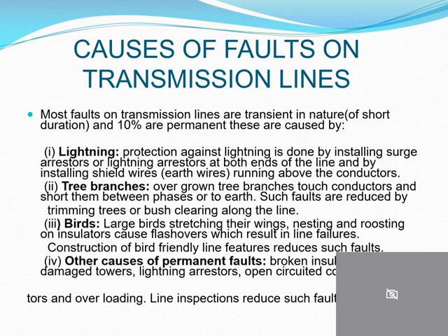When lightning strikes your conductors, it is breaking down your conductor strength, and it can bounce. They're not usually built up in these nice fancy places that your distribution lines get built in. And due to this, we always recommend that bush clearing is something that needs to be done at least once a year, to make sure that we protect those transmission lines.